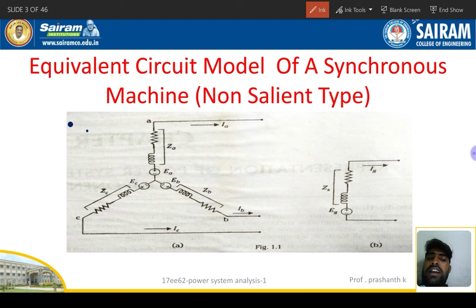You can see the block diagram of a hybrid car. There we are using a synchronous generator or alternator, because there is an engine, petrol or diesel, a 4-stroke or 2-stroke engine, whatever it may be. The engine gives a mechanical output, and that mechanical output is coupled to the synchronous generator shaft or alternator shaft. The alternator's input is mechanical and its output is electrical.